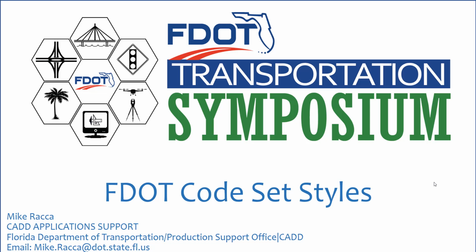In this session we're going to cover multiple code set styles that are available in the FDOT Civil 3D State Kit. We will learn how to apply code set styles, create code set styles, and learn how they are used in various ways in a project, whether you're applying them to a 3D corridor, cross sections, or assembly components.